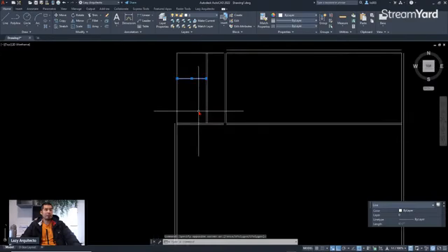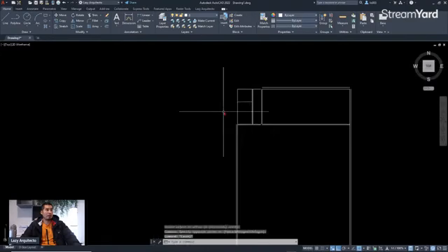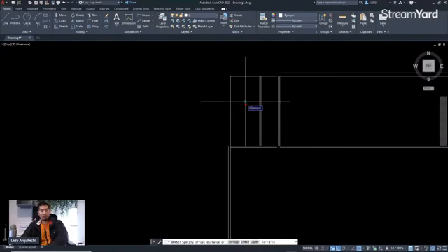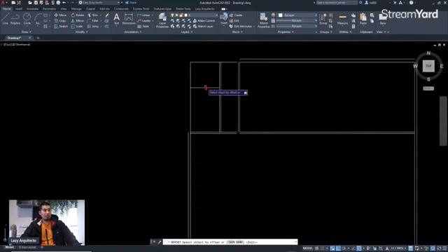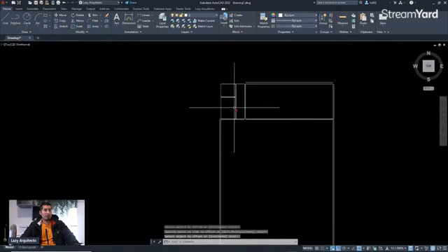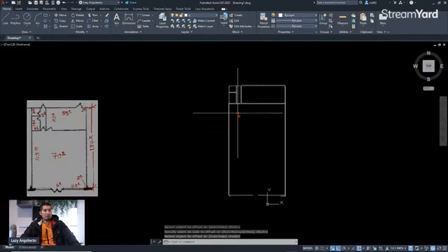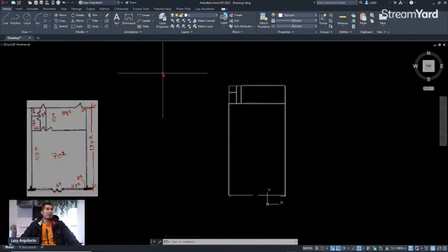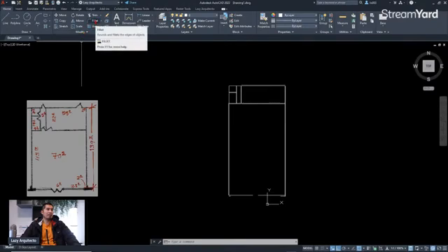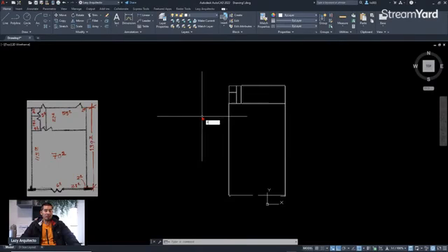So what we're gonna do is we're gonna offset 5 inches, set it down, and then we're gonna introduce you to another command which is called fillet. The fillet command, again, you are modifying something here, so it's gotta be on the modify panel right here, fillet, or you can use its shortcut F and press enter.